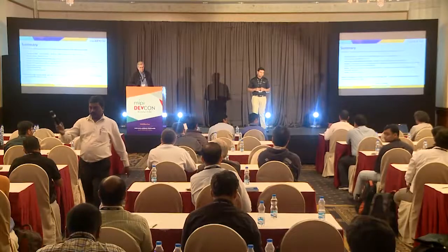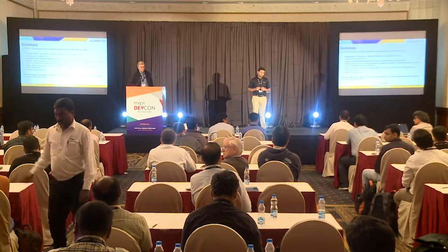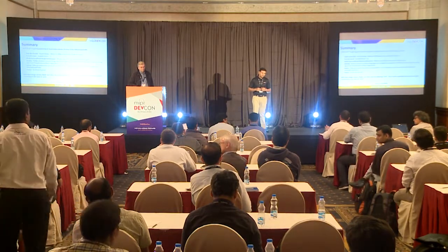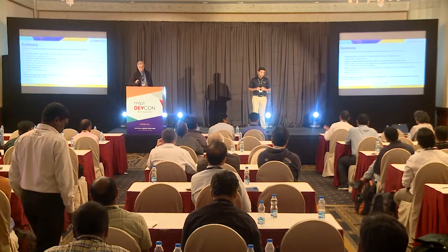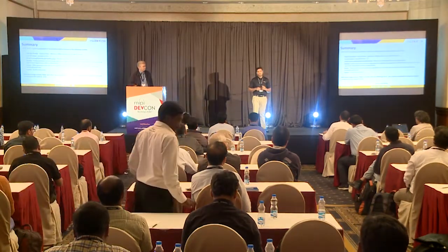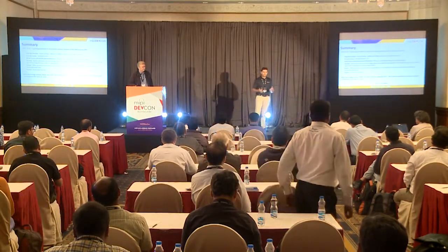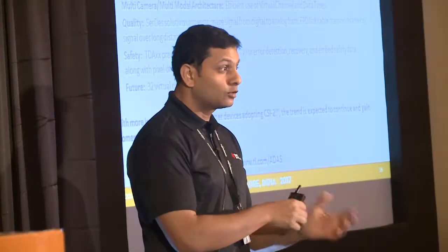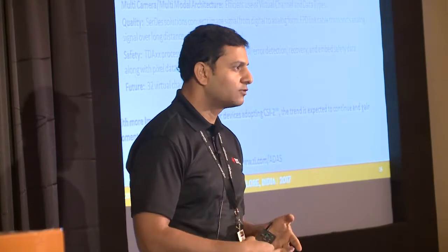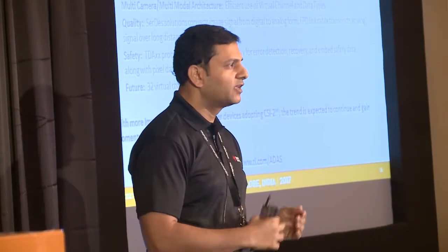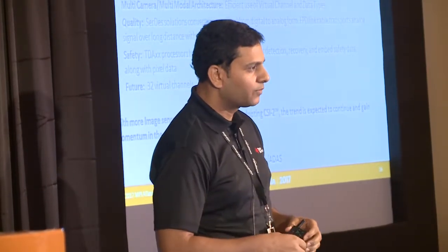Actually, I wanted to ask the same as the previous question. What is the protocol between the serializer and the deserializer? Is it proprietary or is it something like Ethernet? No, it's not Ethernet. It's FPD-Link, which is not proprietary. And TI is not the only vendor supplying that. There is Maxim, and I think there are some other vendors also doing that. So FPD-Link is fairly common.